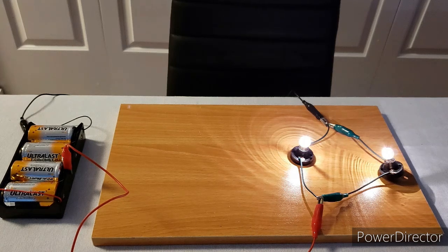The reason for this is because both light bulbs are connected directly across the source. They both have 3 volts across each light bulb. As a result, the same amount of current is flowing through these 2 identical light bulbs. And that's why when you connect light bulbs in parallel with each other, the brightness is the same. It doesn't reduce because the voltage across each light bulb is the same, which will induce the same amount of current, assuming the 2 resistances are the same for each light bulb.